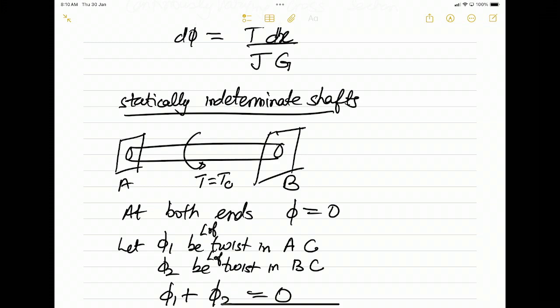They are the only stresses which come on a plane perpendicular to the axis of the torque. So that is why we are considering this case. The more complex cases we will not consider. If the section is not circular or not axisymmetric, we will get other components also, because then sections will not stay planar. There will be out of plane deformation also.